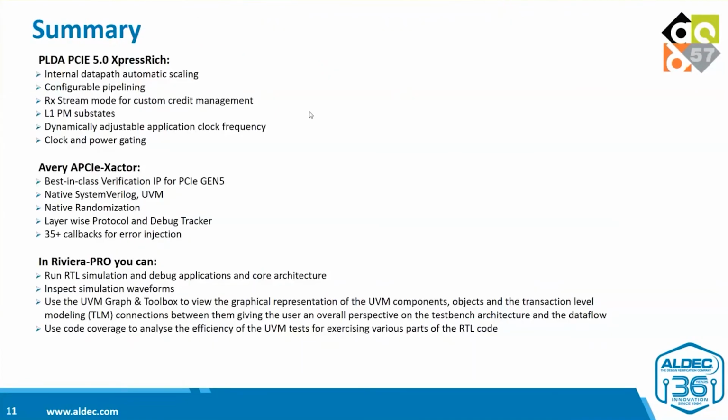Hello, from the summary of today's demonstration, combining the PLDA, Avery, and ALDEC. So the PLDA PCIe 5.0 XpressRICH core is basically a highly configurable core where the internal data path scaling is possible, and configurable pipelining and RX stream mode for custom credit management, and L1 PM substates is supported, and dynamically adjustable clock frequency and many more other features, and latest TCNs and clock and power gating are supported in this IP.